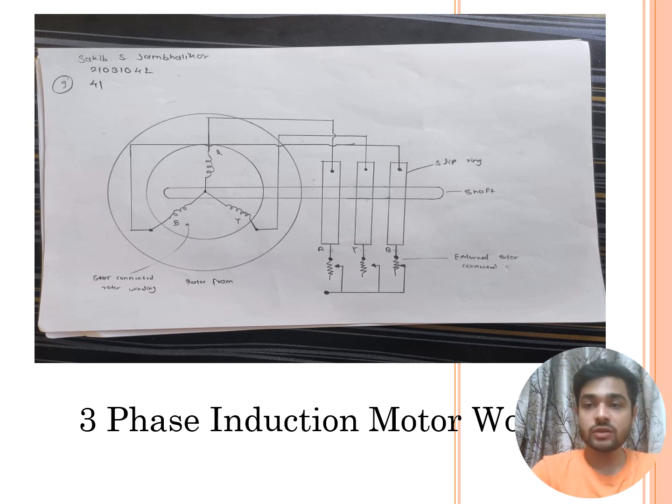The rotor of the three-phase induction motor consists of a cylindrical laminated core with parallel slots that carry the conductors. The conductors are heavy copper or aluminium bars fitted in each slot and short-circuited by end rings. The slots are not exactly parallel to the axis of the shaft, but are slightly skewed. Because of this arrangement, they reduce the magnetic humming noise and avoid locking of the motor.